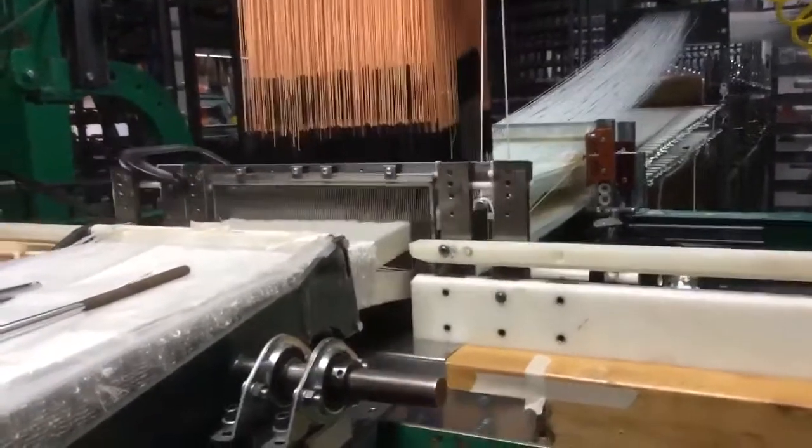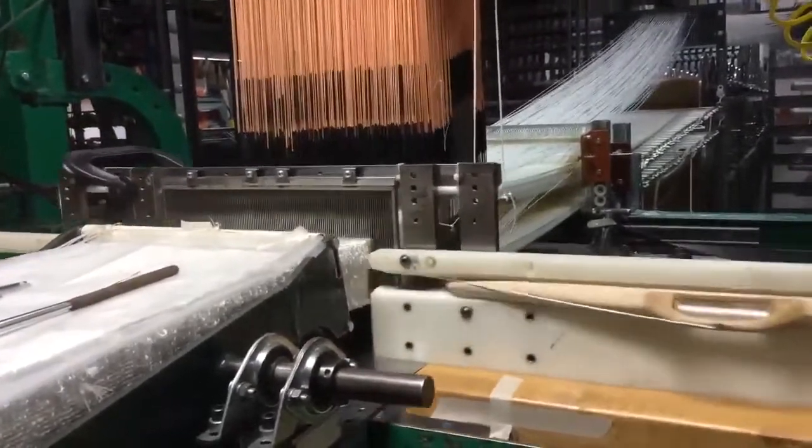And I have one more video I'll show that may be of interest. This is an arc jet test. You're seeing close to a side view of the arc jet article I showed earlier. So this is 4 inches in diameter and a little bit of an oblique side view. And this is 660 watts per square centimeter, so it's extremely hot, very high heat flux in there.